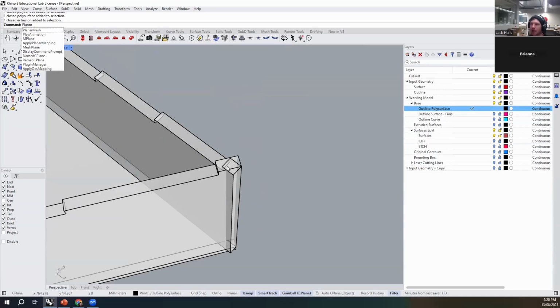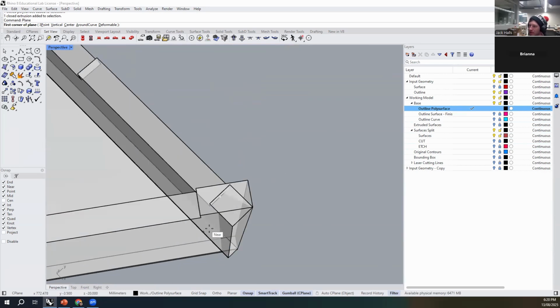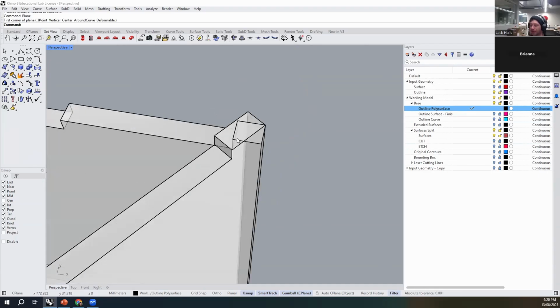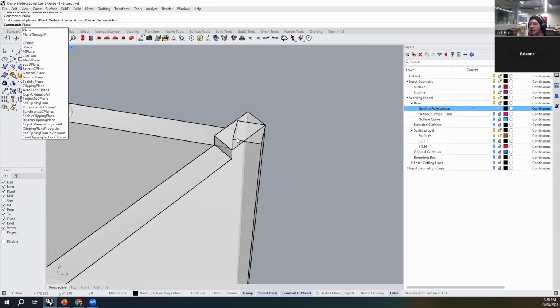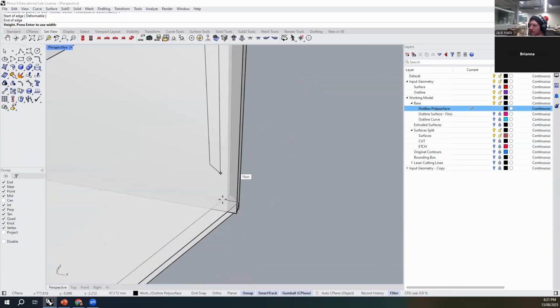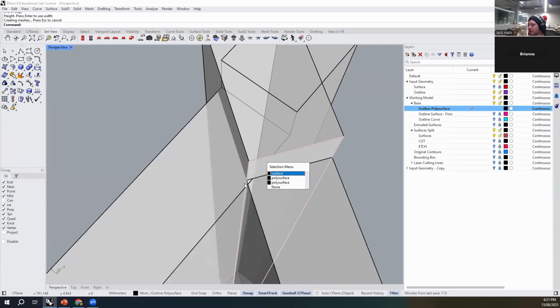But in order to make it more assemblable, we're just going to cut one of these surfaces back to its minimum dimension. In order to do that, just rotate this around a little bit better. We're going to use the plane command, P-L-A-N-E. Hit enter, and I'm going to use V, enter for vertical again. Just select 2 points. In this case, it's these points. And I'm just going to create a vertical plane like so. This plane, at the moment, you can see how it's intersecting here.